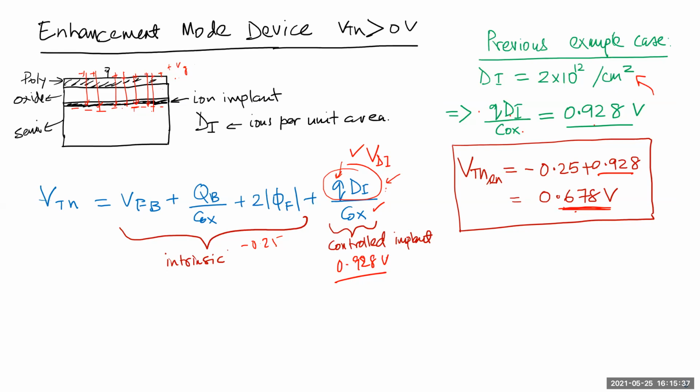So yeah, you use the mask to do the VT adjustment, but you want to make sure the VT adjustment is done only on the channel area, not the other areas. You can do it on the source and drain areas because you're doing ion implantation of the same type as... well, is it the same type, P plus? No, you have to...